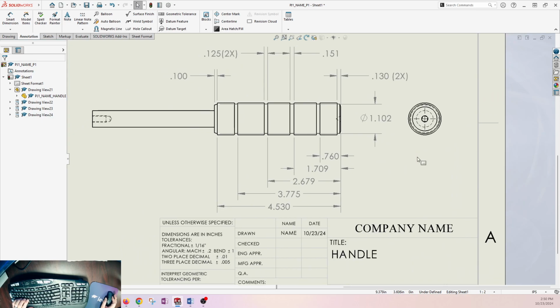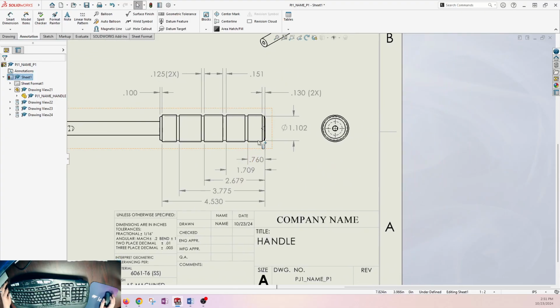So now I don't need to dimension that shoulder unless it was important, which it's not, because this dimension plus that tells you where that ends. Wow. So there's this method that shows them where to start each cut, and there's the width of the cuts. That's one way.